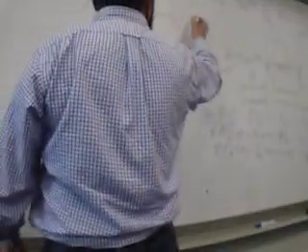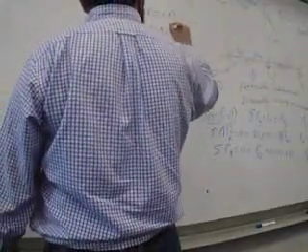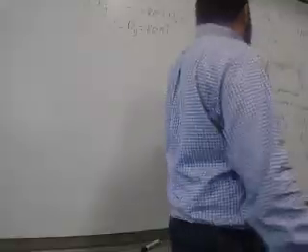Then, sigma Fy for the whole structure equals 0 equals the negative 80 that I have just got plus Dy, and there is nothing else, plus the 0, which is Ay, and there is no other load. Therefore, Dy equals 80 kips up. After that, if you want to solve it with the method of joints, take these ones and these ones.